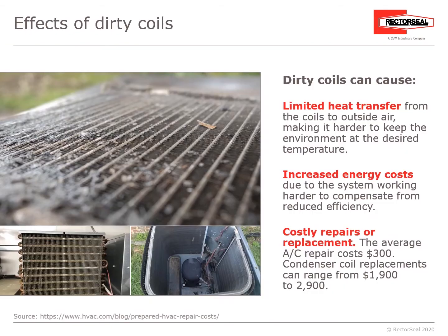The effects of dirty coils, condenser coils and evaporator coils. Having dirty coils can cause limited heat transfer from coils to outside air, making it harder to keep the environment at the desired temperature. Increased energy costs due to the system working harder to compensate for reduced efficiency. And costly repairs or replacement. The average AC repair costs $300. Condenser coil replacements can range from $1,900 to $2,900.